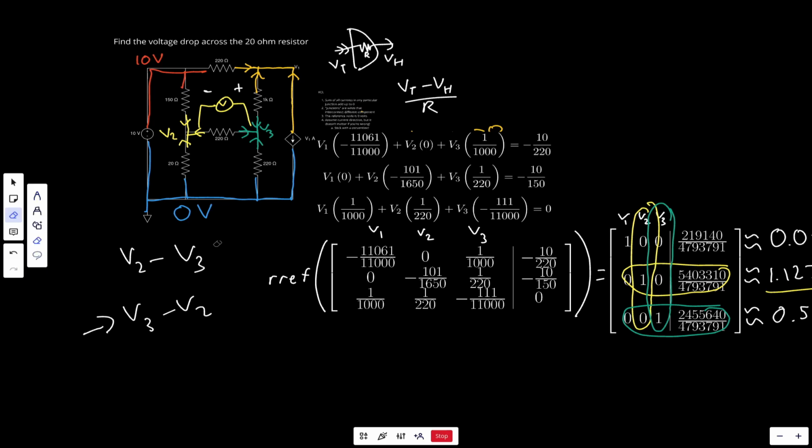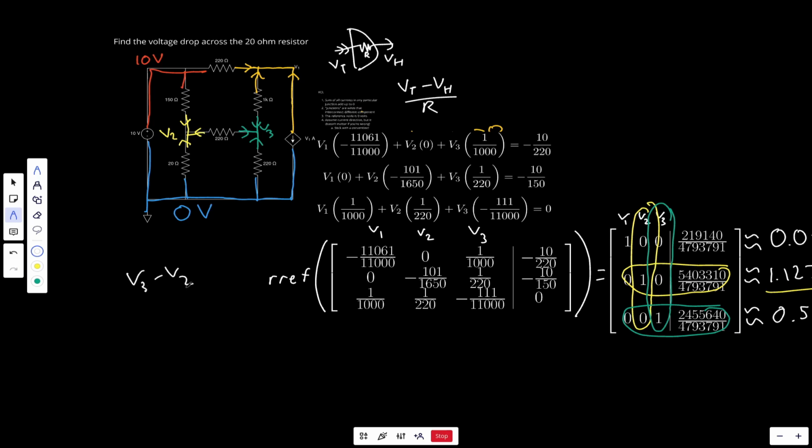Right, so now that we know the basics of voltage and acquiring voltage levels, what happens if we're told to find current? For example, if I said, what is the current through the 220 ohm resistor? Easily, we could just take V3 minus V2, whatever that is going to be, over 220, and we can tell whether it's actually flowing from V3 to V2, because we're assuming V3 is higher. So is it flowing this way or is it flowing this way?